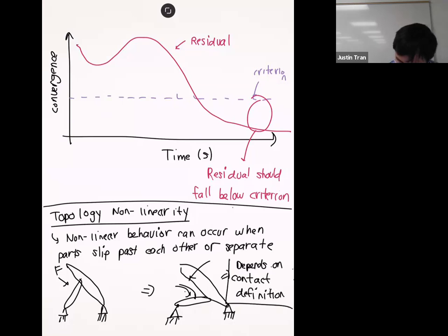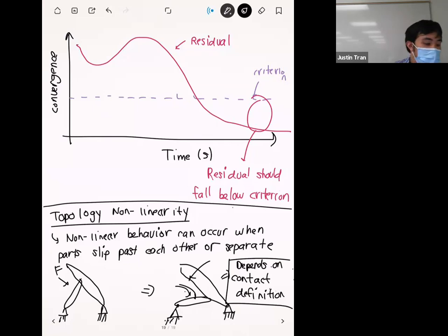One thing I want to cover today is, we're going to go through the list of all the different contact types that you can use, which ones introduce nonlinearities, and what you can expect from the behavior of each one. Any questions on this? All right. So let's go through the list of the different contacts that are available within ANSYS.